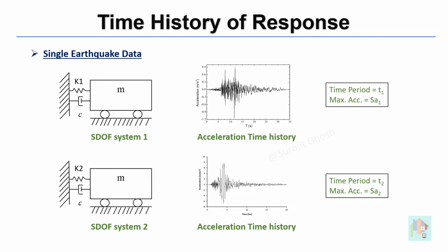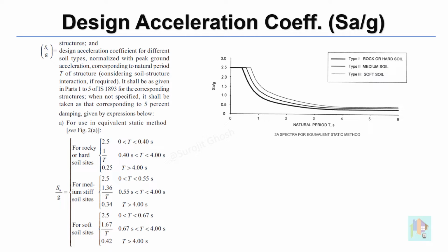In part 3, we had a detailed discussion on how earthquake ground acceleration data is simulated on different SDOF systems with different time periods, and the maximum normalized response is recorded in this design spectra curve. We can use this to find the design acceleration coefficient using the exact time period of the structure. As the slope of the curve changes drastically in a few regions, it is very important to calculate the natural period accurately, else incorrect seismic force will be considered for design.